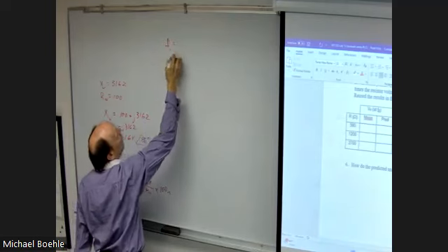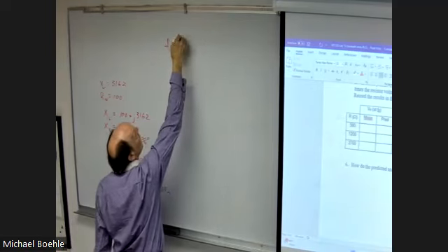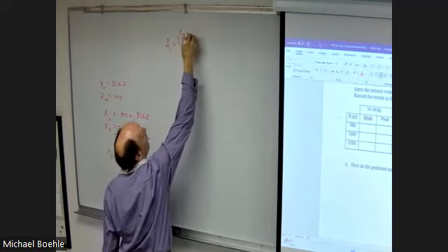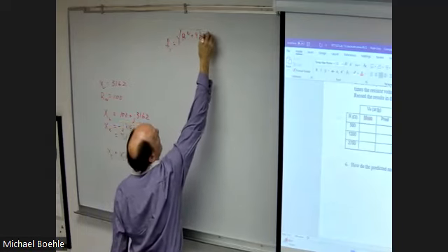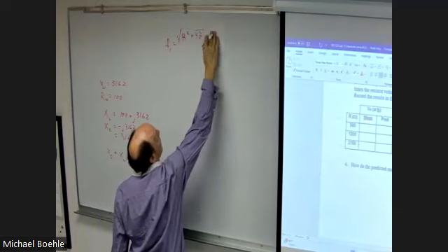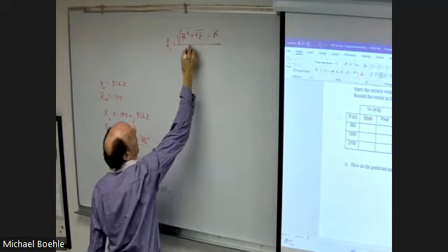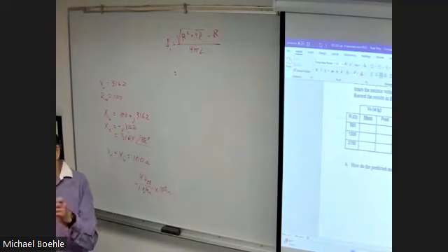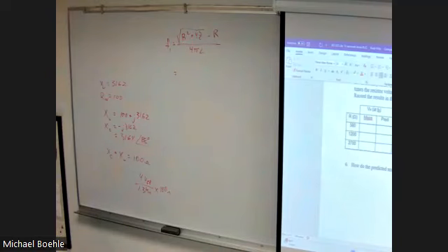So the lower cutoff frequency will be the square root of R squared plus 4 times L over C, minus R, divided by 4 pi L. Now, realistically, let's just use the resistance of the inductor plus our resistor.